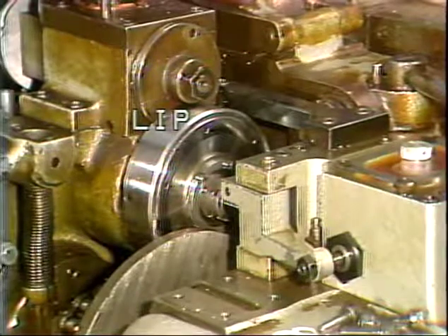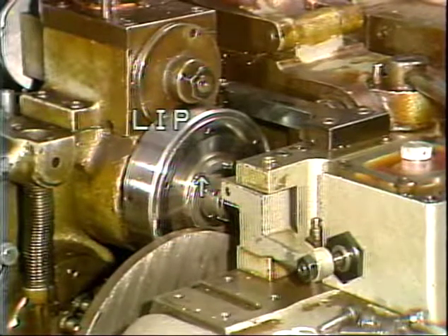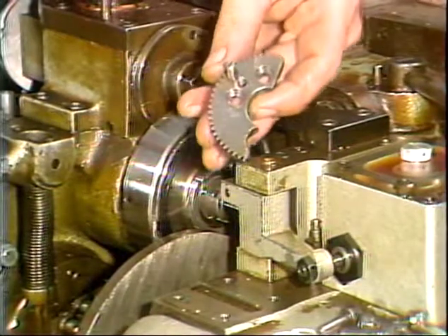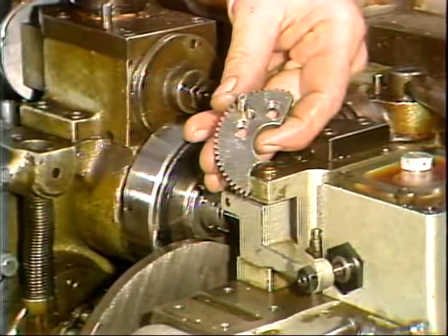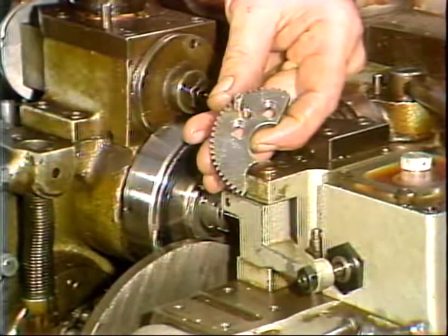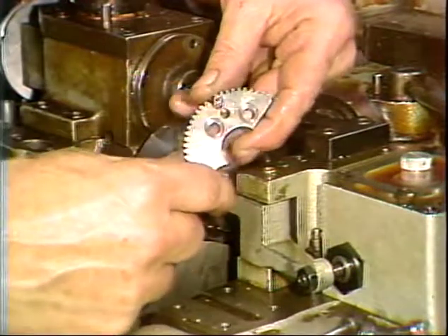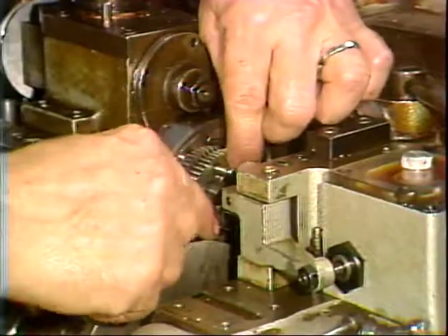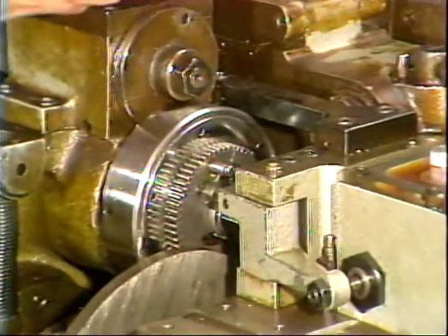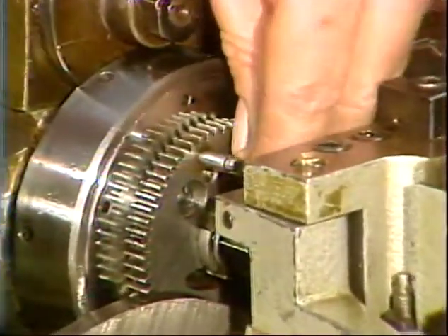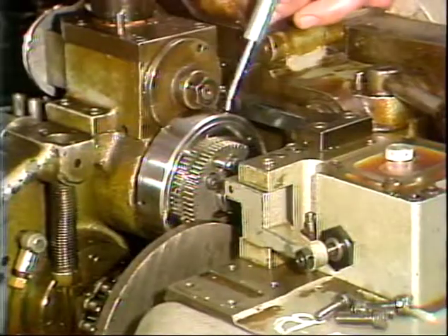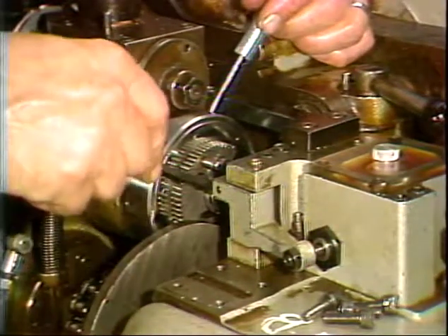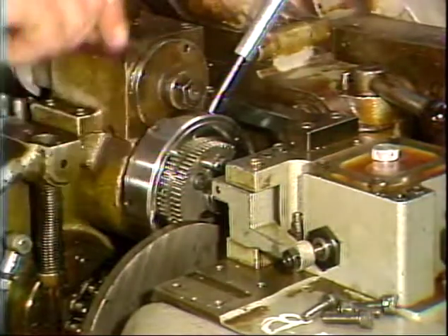The half-circle gear mounts to the friction clutch. You must align this lip on the friction clutch to the groove on the back of the half-circle gear. Mount the gear and align the 2 mounting holes in the gear to the holes in the friction clutch. Install the 2 mounting bolts and tighten. Insert a pin into a hole in the friction clutch drum to keep the drum from rotating while tightening the mounting bolts.